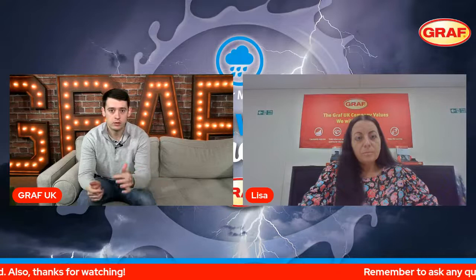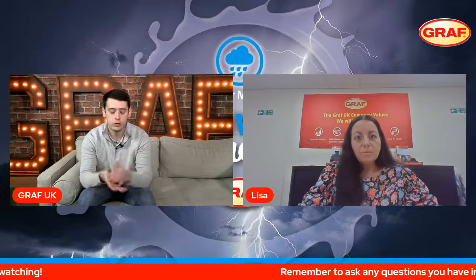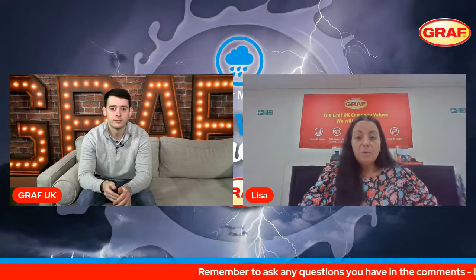Perfect. And when you talked about our tanks, we specifically make sure during install that they're heat welded. So what are the typical tools that we use in order to weld the tank together? The main thing we use is a wedge welder. Obviously, we overlap the membrane, and we use a special tool called a wedge welder, which basically goes into the two sections of the joint and then runs automatically down and seals the two together.